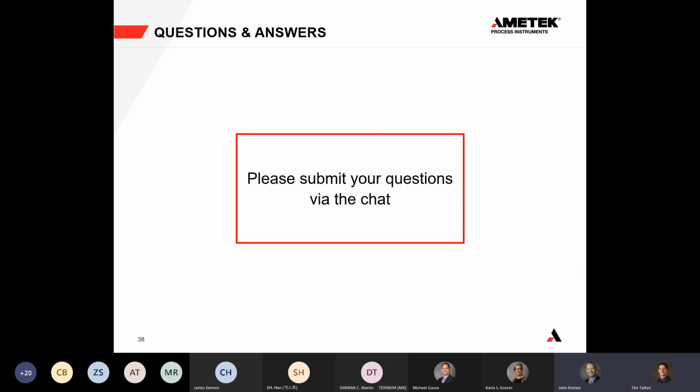Sure, and let me know if you have any other questions after I answer this. I certainly understand that transitioning fuels is a business case in and of itself, let alone all of the design work around it. But what I will say is that optimized combustion is certainly one way that you can leverage your heater as is, leverage your boiler as is, to ensure fuel efficiency, ensure energy efficiency within the plant. Same with waste heat recovery, as I mentioned before. Now, with reliability,